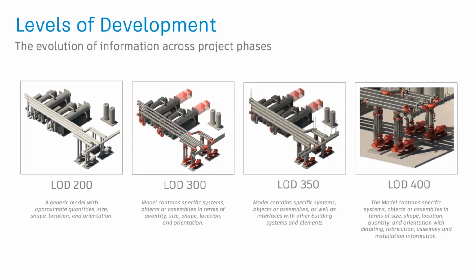And then as it gets increasingly more detailed and maybe passes from design to contractor, we start seeing the models being enriched. The goal really is to not have a design model, throw that away, and the contractor then starts with something else, which has historically been the case. The idea is to move the technology forward and add levels of information as they become available. So as you get to an LOD 400 stage, you've got a model that contains enough information to support the detailing phases. You can export that model for fabrication.